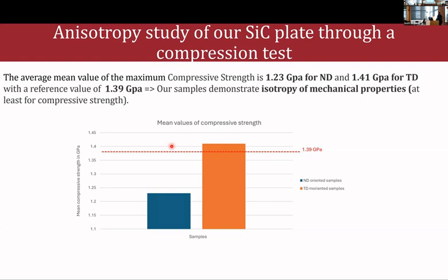But your error bars are huge. Yeah, the error bars are huge. These are compressive tests. I've done compressive tests on ceramic, so the surface flaw issue should not be a very big deal in a compression test. What becomes a bigger deal is the parallelism of the top and the bottom of your sample.